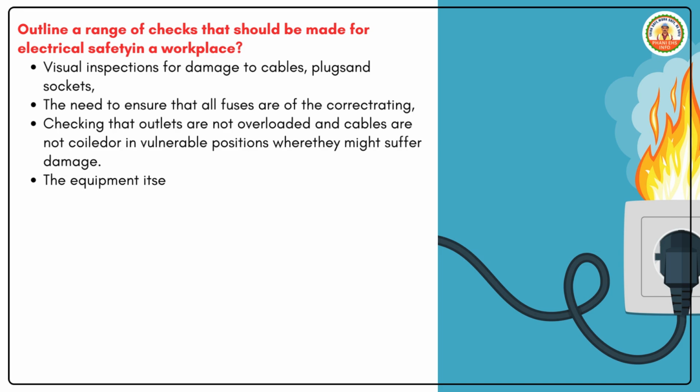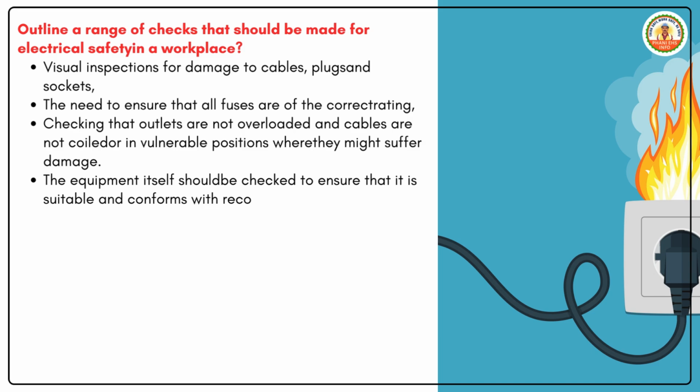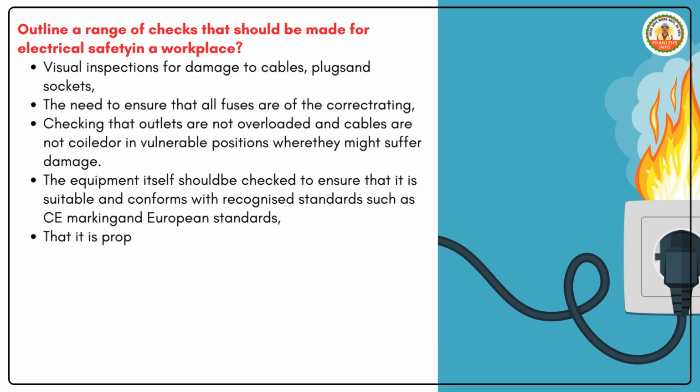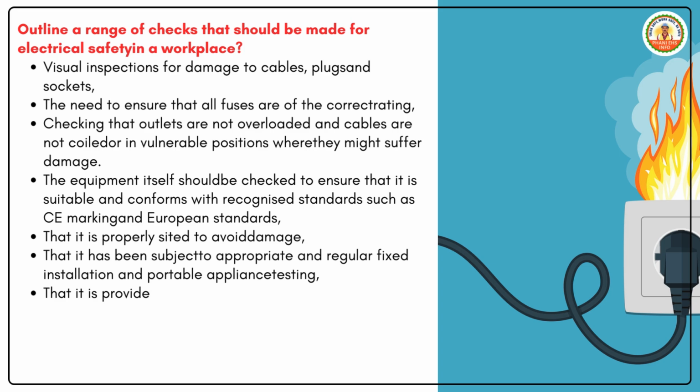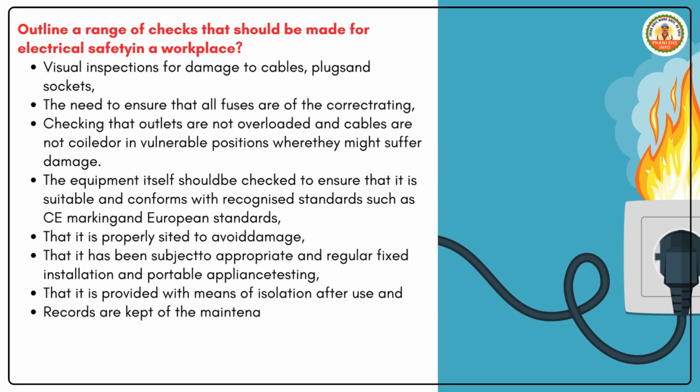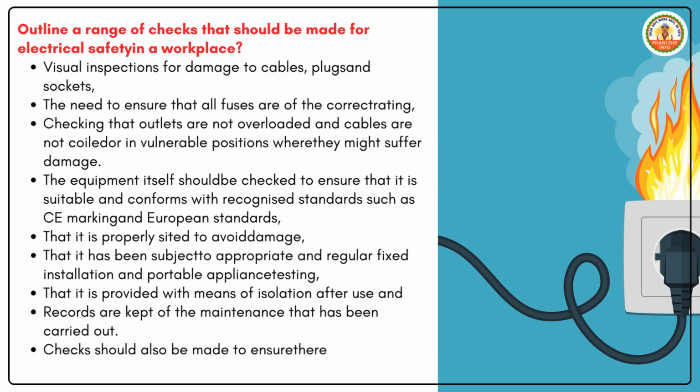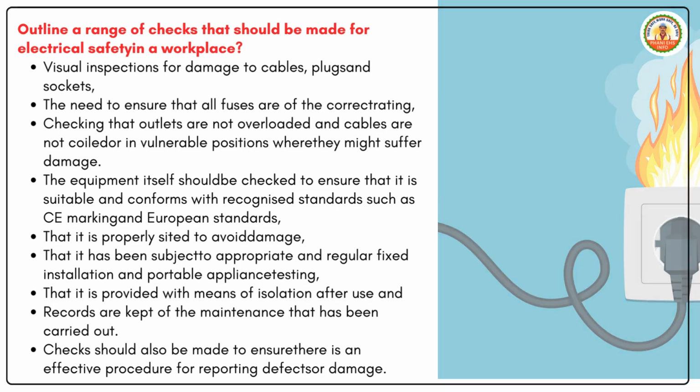The equipment itself should be checked to ensure that it is suitable and conforms with recognized standards such as CE marking and European standards. That it is properly sited to avoid damage. That it has been subject to appropriate and regular fixed installation and portable appliance testing. That it is provided with means of isolation after use and records are kept of the maintenance that has been carried out. Checks should also be made to ensure there is an effective procedure for reporting defects or damage.